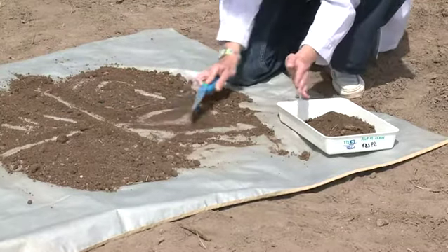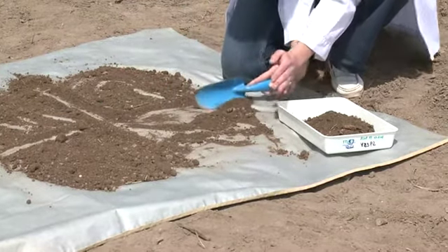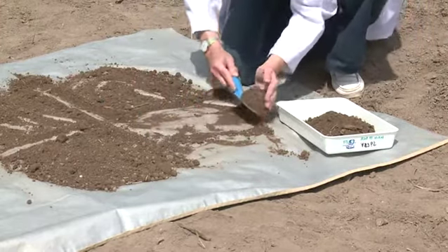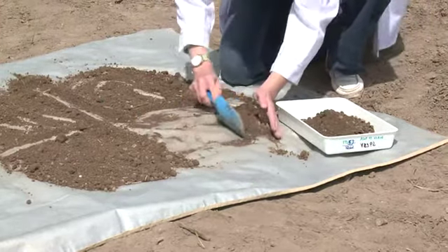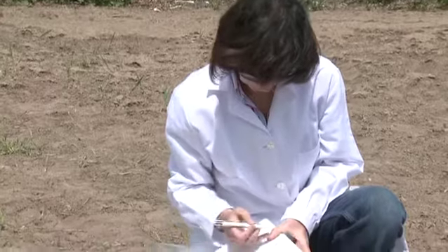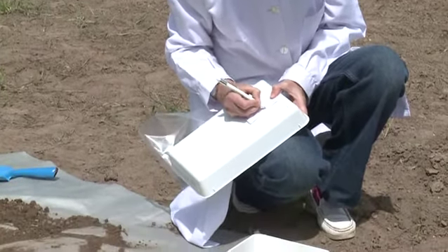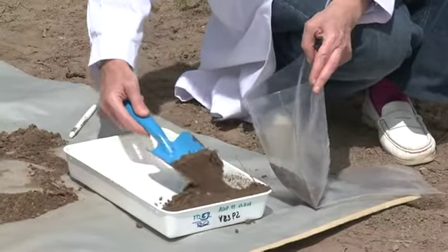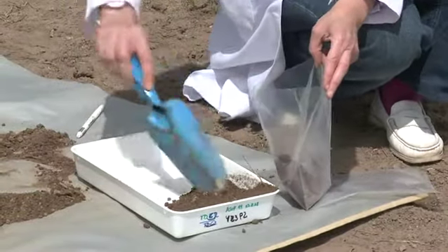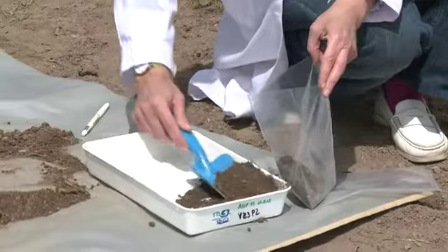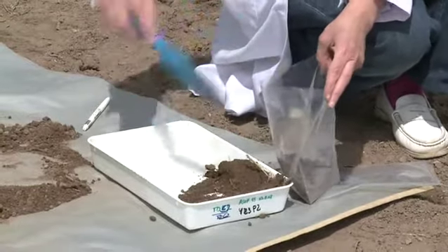If the remaining soil sample is still too big, repeat the procedure. The collected sample is labeled and stored for transport to the laboratory to perform the standard analysis. Half a kilo sample is normally sufficient, provided the soil is not rocky.